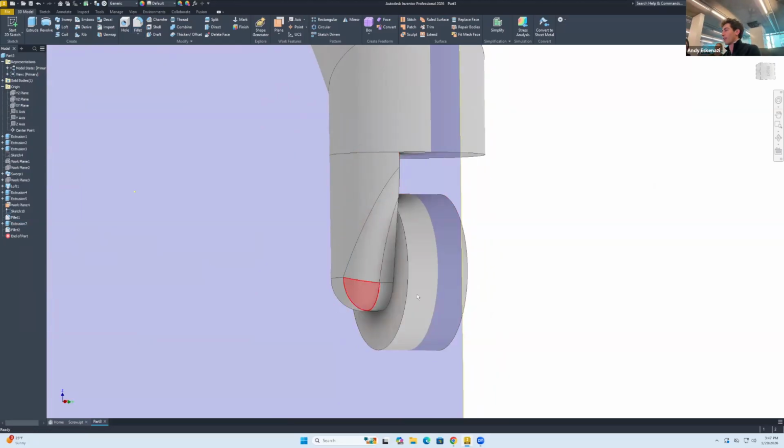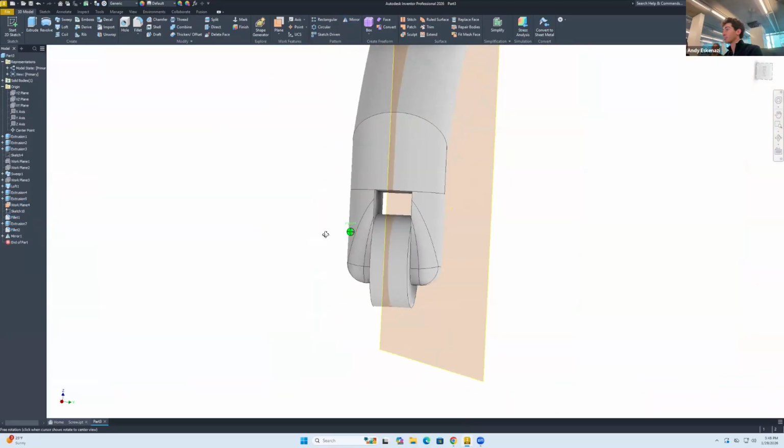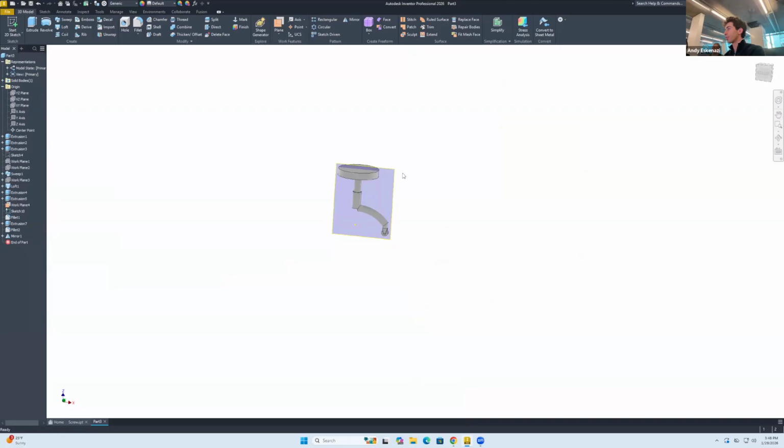No, not after the fact. What I hate the most about Inventor is that I cannot move things on the feature tree in time. So it's okay, this wheel is going to look a little bit sad, but we're going to do a mirror now of the features: extrusion 5, fillet 1, 2, 3, mirror plane, that. Okay. Wow. So now you've got a wheel of our chair. We're almost done, I promise.